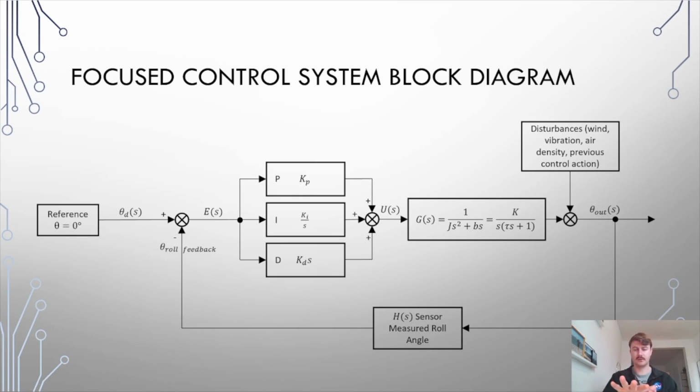So as the body frame gets turned, until that body frame gets recorrected, it will continually send the correction value. So what it does is it has memory almost. If you start here and you turn it here, it will send the control signal until it's rewritten. So that's using the past data.